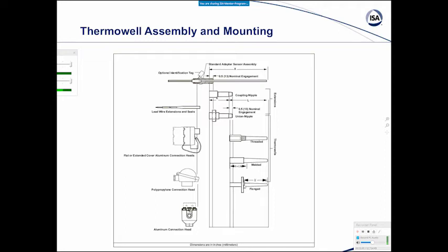And we usually used flange connections as being the one that was most reliably installed, and also probably was in some ways easier to get out, certainly than some threaded ones that got corroded or, due to thermal expansion, caused tightening.